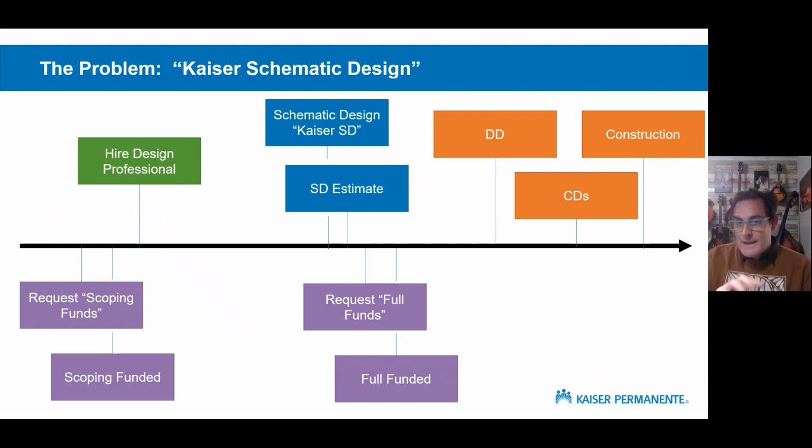In particular, we need to have three things. First, all the equipment sizing needs to be done. There's no preliminary sizing. We need to know what the sizing is going to be. Then second, all the energy effects need to be known. If we're going to achieve energy savings on the project or not, then we need to know that, and we need to know how much. And then thirdly, all the associated issues need to be known and they need to be planned for. So we can't wait until DD to find out that the building has three-way valves that we're going to need to correct, or that there's duct leakage that we need to address, or that there's 7 zones with the cooling actuator out of whack, right? We need to know all that stuff in the SD estimate.